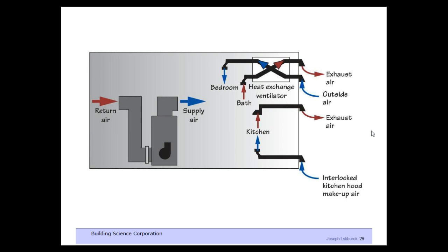This is a much more elegant approach. It provides heat recovery. We're now, in essence, not relying on the air handling unit itself to do this air change. What's nice is that you can get rid of the furnace and air conditioner completely and go with radiant heating or a package terminal heat pump, and the general system works the same.